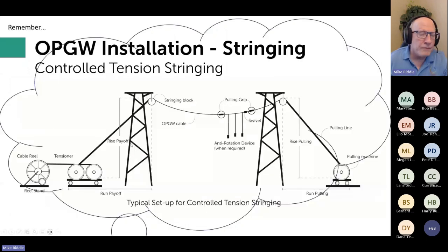They effectively require proportionally much more force to get them moving, and have a smaller contact surface area. Plus, when you're stringing, you get a little bit of friction at each block. But with those smaller blocks, it's taking even more force to get them moving.